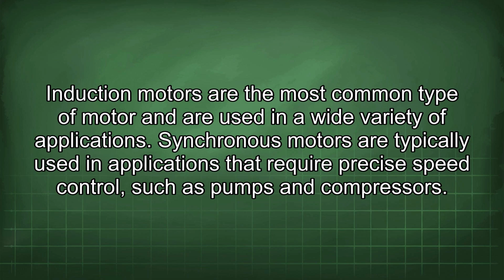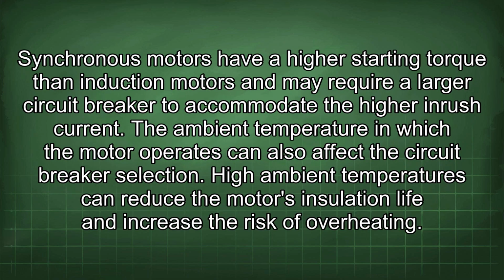Synchronous motors are typically used in applications that require precise speed control, such as pumps and compressors. Synchronous motors have a higher starting torque than induction motors and may require a larger circuit breaker to accommodate the higher inrush current. The ambient temperature in which the motor operates can also affect the circuit breaker selection. High ambient temperatures can reduce the motor's insulation life and increase the risk of overheating.